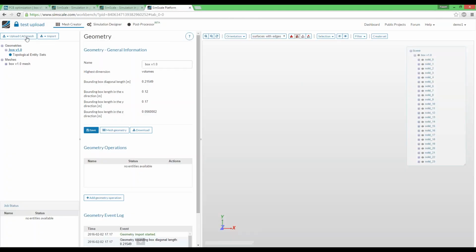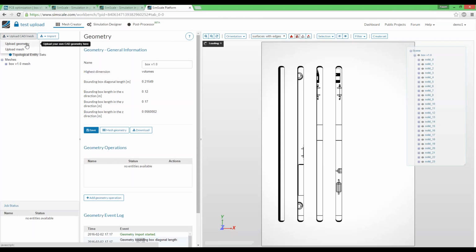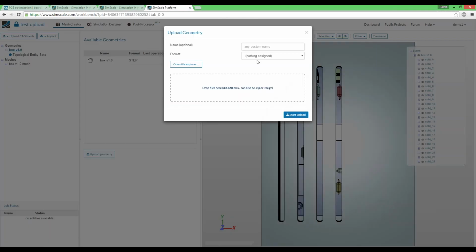You can also upload your CAD designs and geometries from files stored on your computers using STEP, IGS formats, BREP for people who are familiar with Salome, and STL, which I would definitely advise you to go with STEP or IGS, since STL will only carry the information about the surface and it does not group the faces themselves, just the triangularization of the shape.